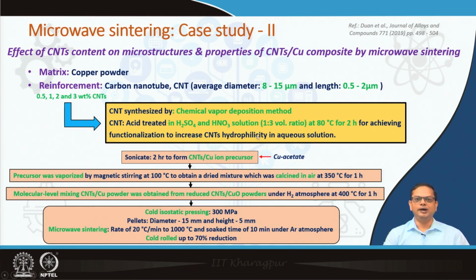So, oxygen atom containing functional groups get attached on the surface of CNT, and those functional groups improve the homogenization of the CNT particles when they are getting distributed or mixed with some other particles. There will be a repelling action between these functional groups, being similar functional groups. So, they will repel each other, which means the CNT particles will be pushed away from each other. Also, these functional groups help in improving the wettability when these are mixed with other matrix material.